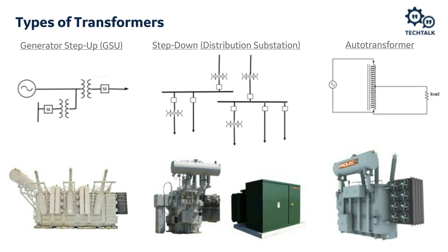So if a fault does occur on the load side, it'll be directly reflected to the source side. And if a winding fault occurs, full input voltage could potentially be applied to the secondary system, which could be very damaging. Because there's no isolation, the secondary side will still see the transients and harmonics from the primary, and proper grounding can also become a concern. In certain cases, an auto transformer may still be more economical, and where those are used, most mid to high-end protection relays will still support them.